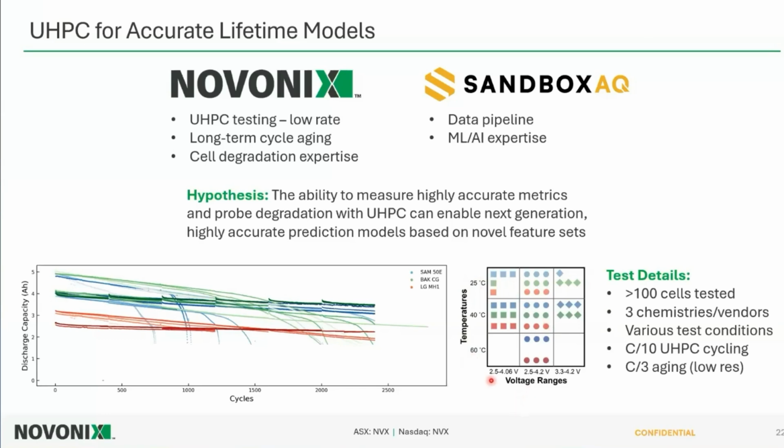And then operating in different voltage ranges, say from 2.5 to 4.06 volts, cuts out that last lattice contraction in high nickel cathodes, which can really mitigate some of the failure mechanisms that those high nickel cells may experience. And then doing the full range, and then also operating from 3.3 to 4.2 volts. So this is actually cutting out some of the silicon-based capacity in the lower states of charge, so that we're not actually expanding and contracting the silicon and losing lithium to those SEI-based reactions. So this matrix of different testing conditions really gives us a challenging generalizable case to try to predict lifetime with.